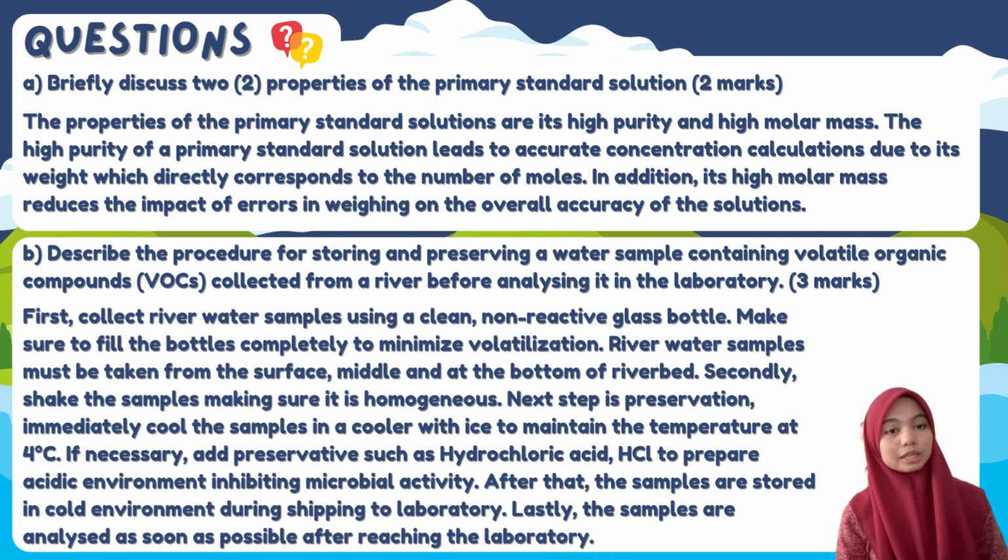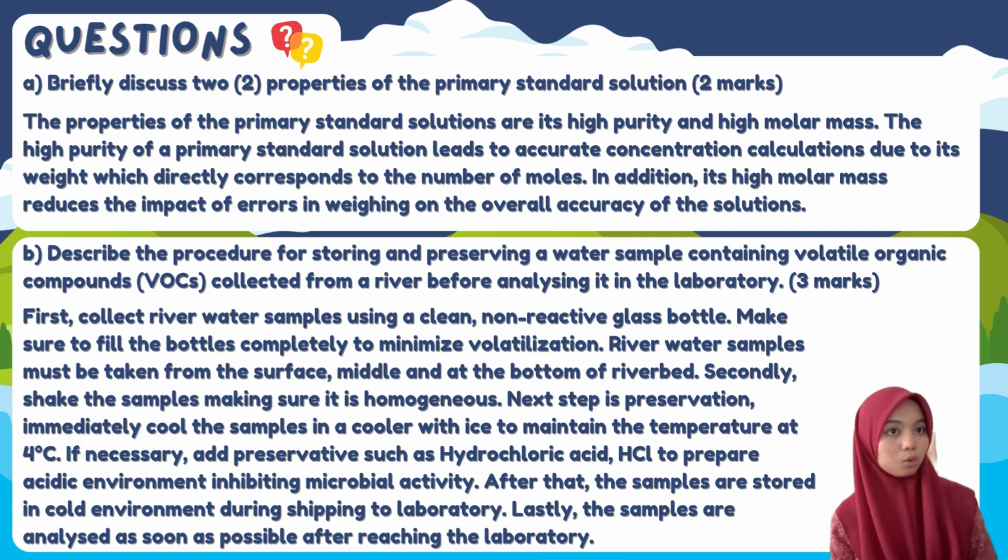Next, I'm going to answer the questions given for our topic, which is sampling water samples for wastewater treatment. The first question is: briefly discuss two properties of a primary standard solution. The properties of a primary standard solution are its high purity and high molar mass. The high purity of a primary standard solution leads to accurate concentration calculations due to its weight corresponding to its mole. In addition, its high molar mass reduces the impact of error in weighing on the overall accuracy of the